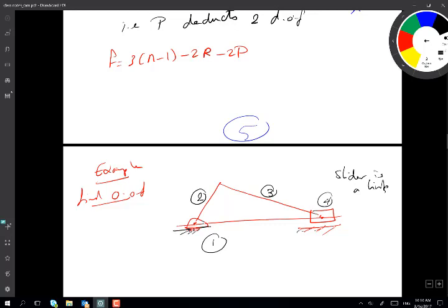How about the joints we have in this linkage? This joint allows the angular thing to happen. That's R. Another R, because this angle changes. If the angle changes, that's an R. And also here, because this angle changes, that's an R. And this one here is prismatic. That's sliding. So I have n is equal to 4, revolute joints equal to 3, and prismatic equal to 1.